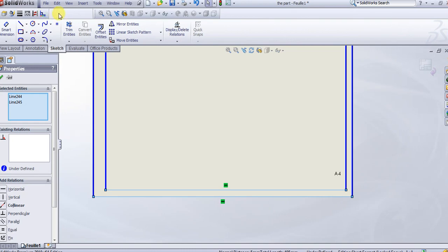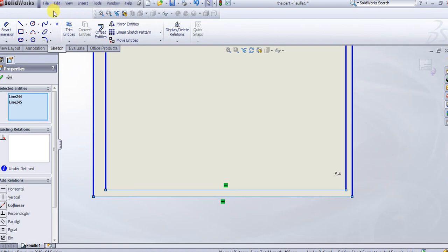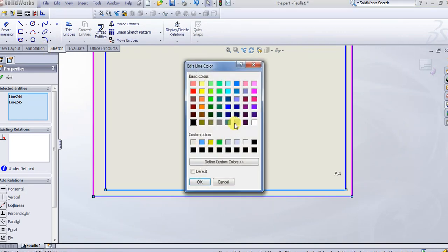We click on the blank space here, we select line format. See, line format. You can edit the thickness, the style, and also the color. Of course I'm gonna choose 0.5 thickness. For the color also I'm gonna choose blue. Sorry, color is here. Blue, like the other one.